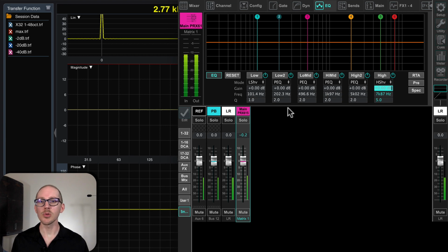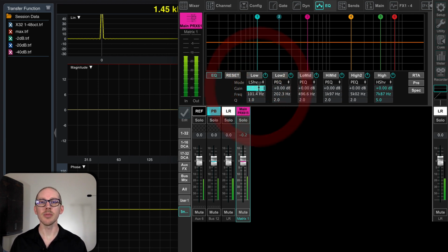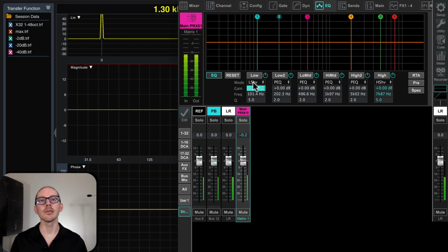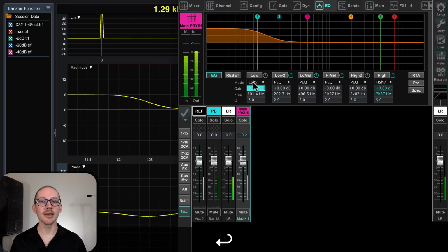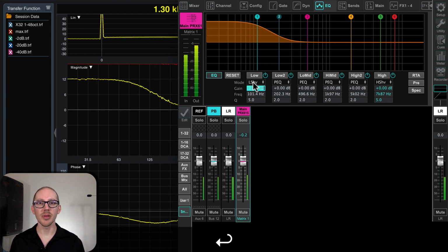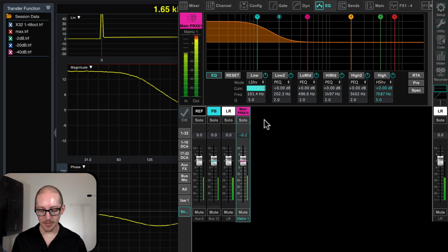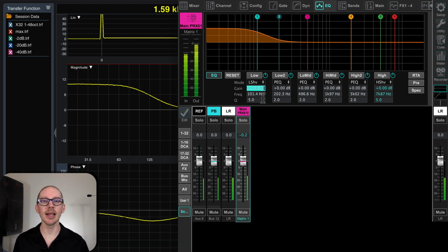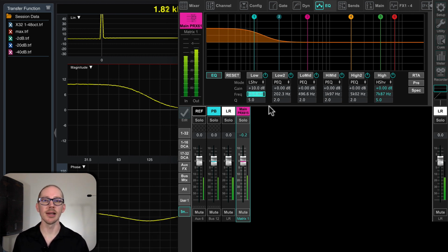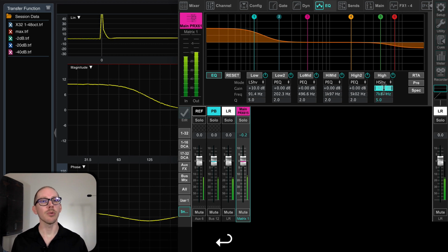So as I mentioned, most people want some low frequency boost. In my case, it's usually about 10 dB. In a lot of concert or theater or circus, you're going to see a +6, +10, +12. Maybe if you're doing an EDM show, +20, I don't know. Okay, so let's leave that at +10 because that's the way I like it. And it started a little bit too early, so I'll just take this down to 90, maybe split the difference there. And then I also mentioned that we generally want some kind of high-end reduction. So I'm going to put in a 4 dB cut.